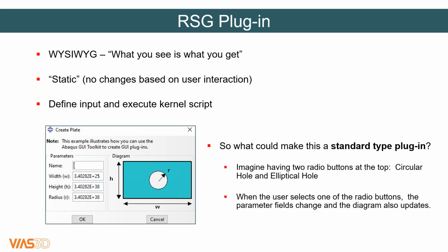If you interact with that Really Simple GUI, what you'll have to do is, as you build your dialog, you also have a tab on that dialog builder where you will connect your kernel script. This kernel script will contain all the commands you want to execute when you hit the OK button.